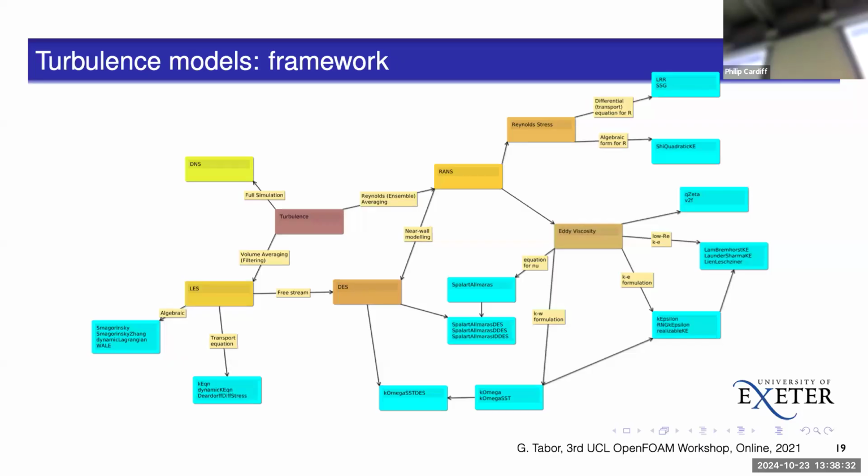We're going to look at what's called the eddy viscosity model. This is the most common approach using the K epsilon. This is the most common type of RANS approach. But there's other types of eddy viscosity models, basically different formulas that you would use. And this K omega SST is kind of, if you don't know anything about turbulence, just use K omega SST. And then Reynolds stress is another variant, which is more accurate but more expensive.